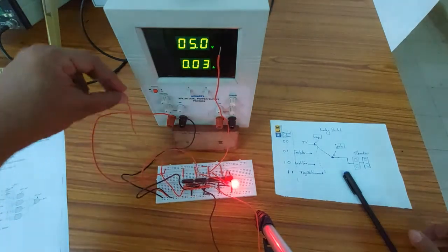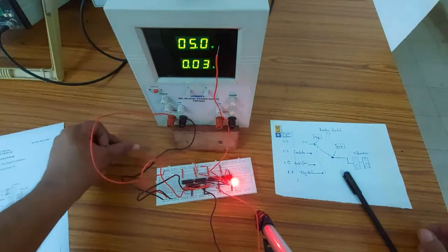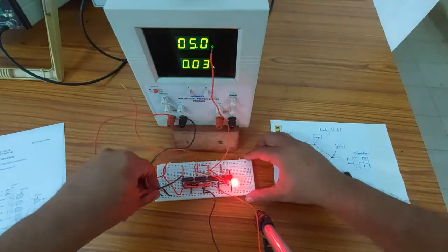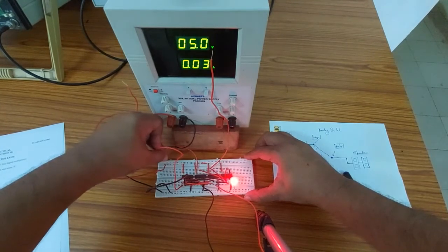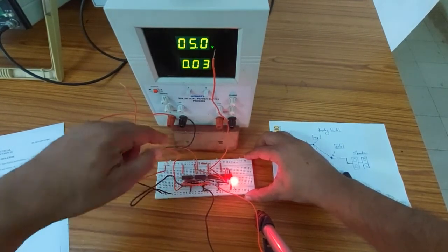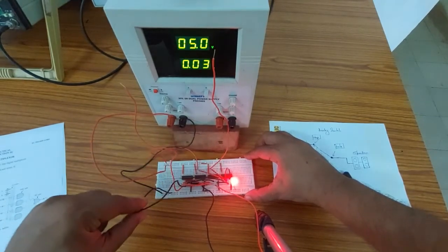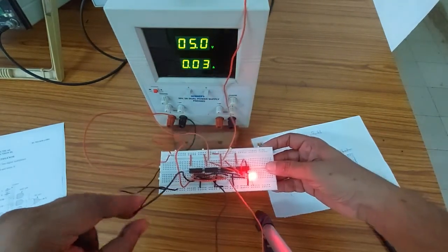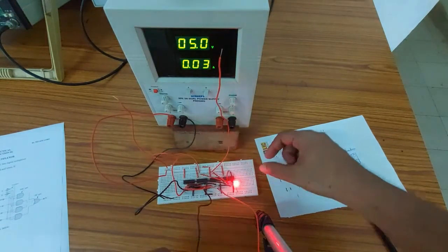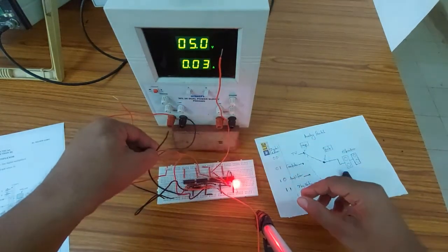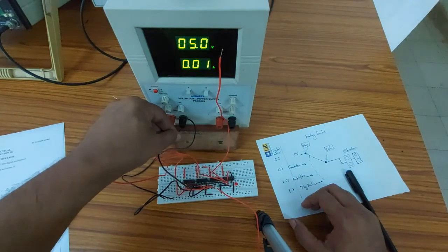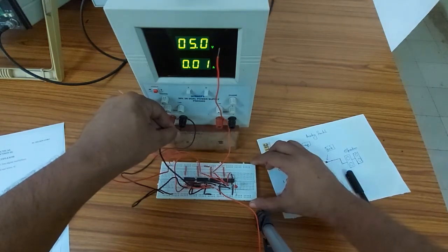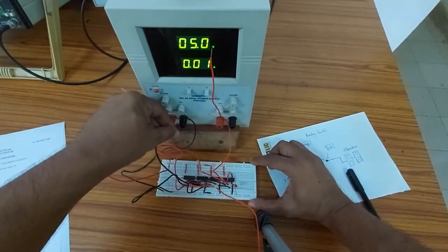The next condition is for using the input D1. So for D1 it is 1 and 0. So I'm putting this line to VCC, the address, so it is 1 and 0. I'm going to use D1. If it is 1, the LED is on. If it is 0, the LED goes off. So I have verified when the address is 1 and 0 that D1 goes to the output.